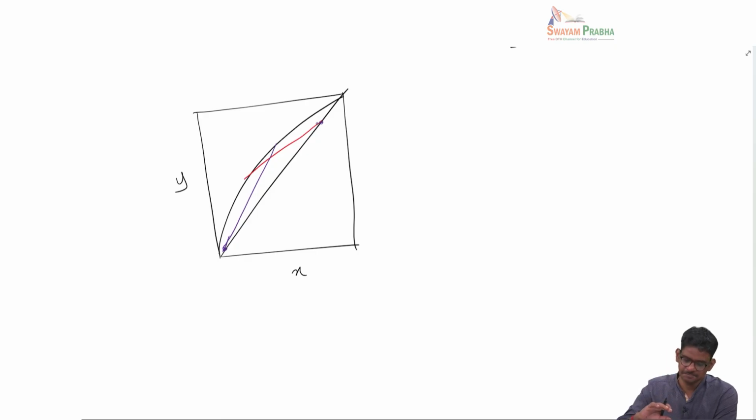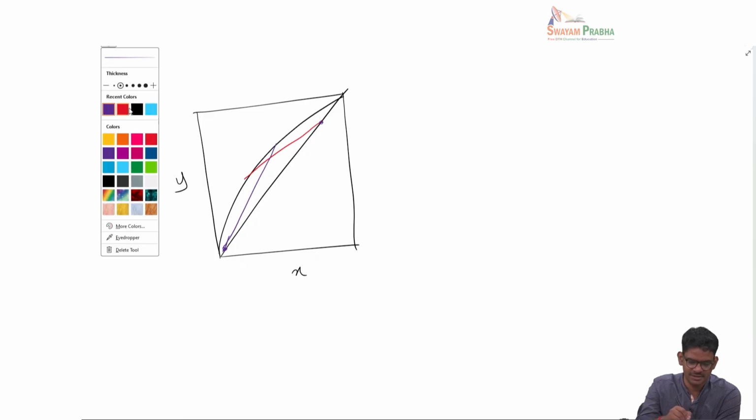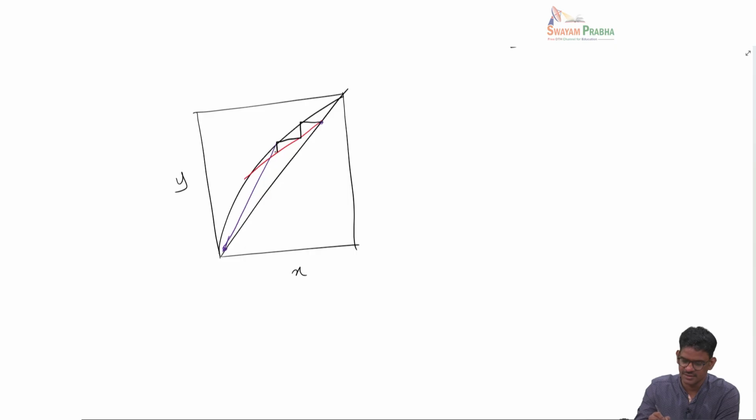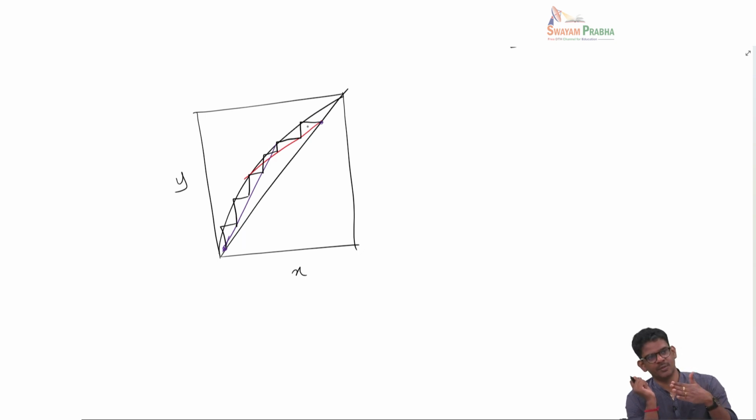So you can see that there is an equilibrium line and two operating lines, and what we would like to do is to start constructing the staircase diagram like this, and then find the total number of stages. Now I have to make a transition from one operating line to the other at the right point, and that becomes a very critical issue. The slope of this line also depends on the reflux ratio I am using, because the slope of the operating line is proportional to the L/G ratio, the liquid to gas flow rate, and that is in turn determined by the reflux.